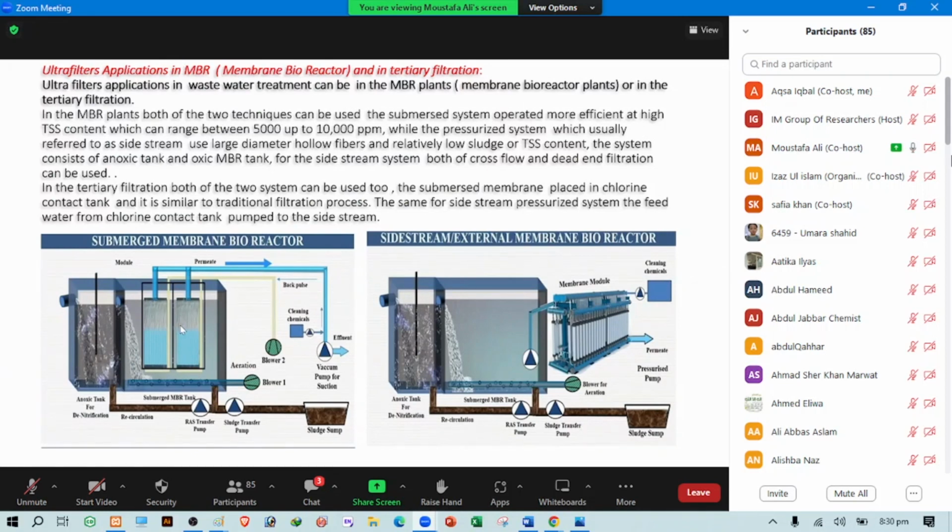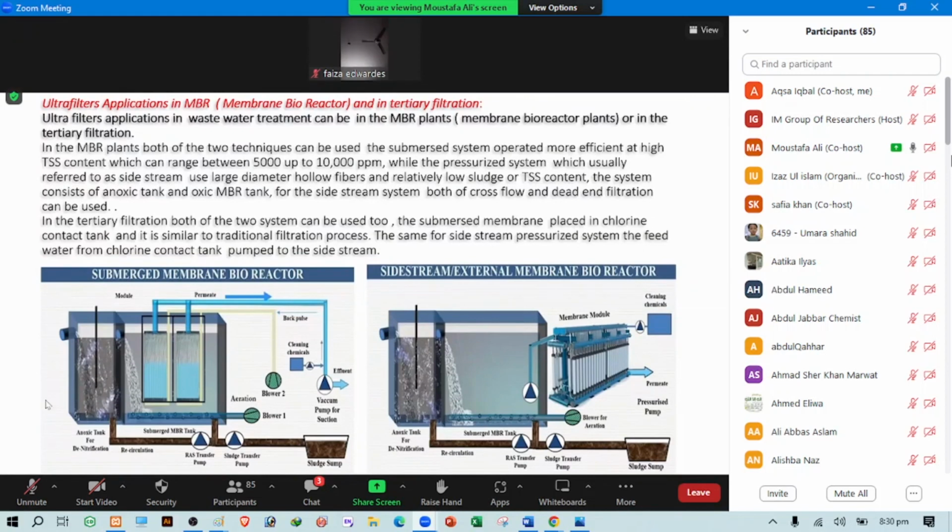So again, we have here the anoxic tank, the raw sewage added to it, and at the same time, as I said, displacing the liquor, or the wastewater, to the next tank. In the next tank, it has continuously increasing, as I said, sludge content, or total suspended solids content. So we have to pump from this tank the liquor inside, the solution inside.